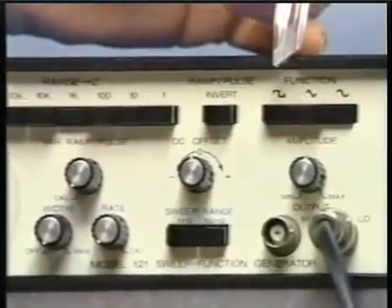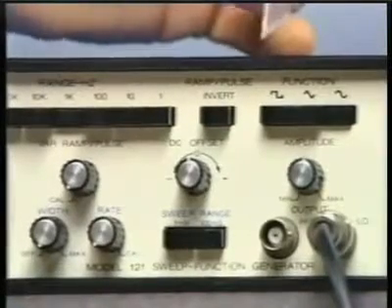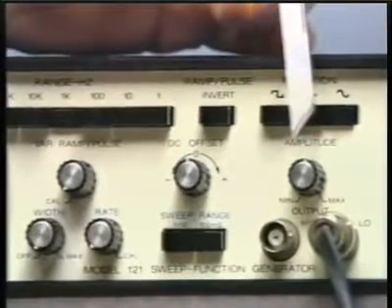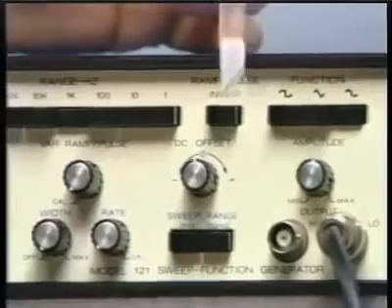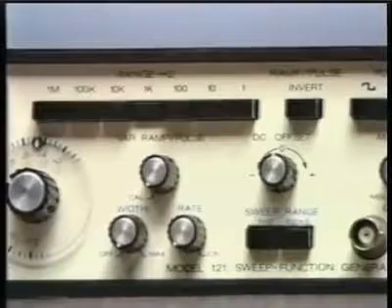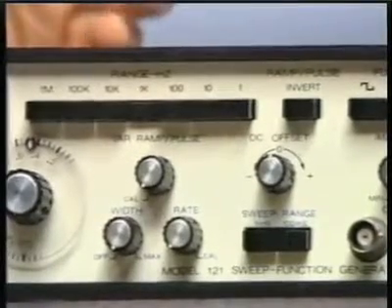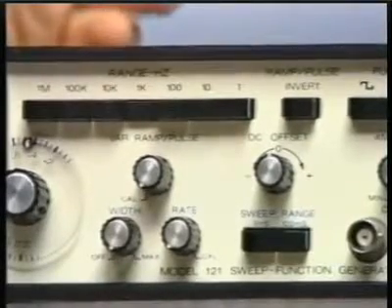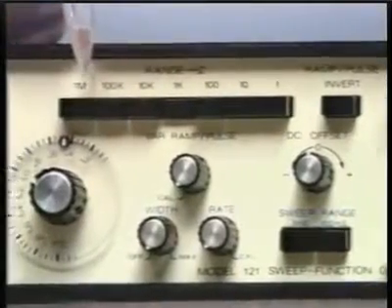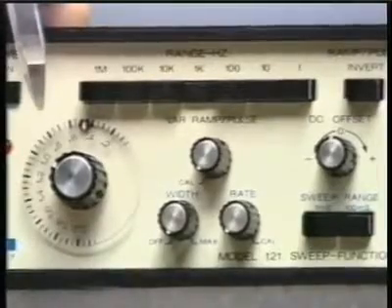The top 3 buttons here allow us to change from one simple waveform to another one, a sine wave, triangle wave, square wave. And right below it is a button that will allow us to change the size of the signal. Moving over towards the left, we can change the DC offset, which varies the level upon which the signal rides. And we'll be using that actually when we demonstrate amplitude modulation. That's right. And then finally, there's a way of changing the frequency of the signal, either changing it by a factor of 10 or a vernier adjustment if you want very specific adjustments, very delicate changes.